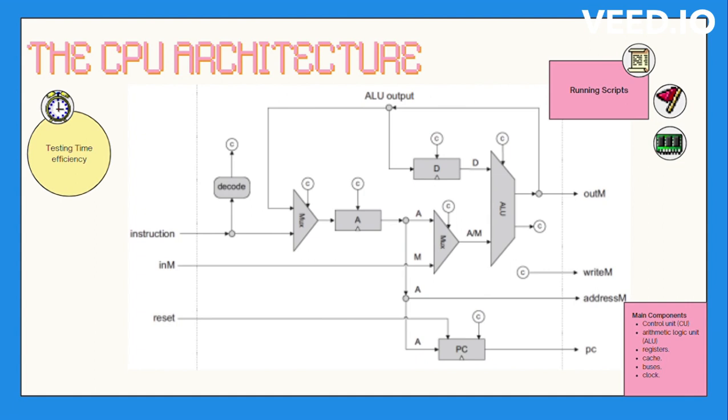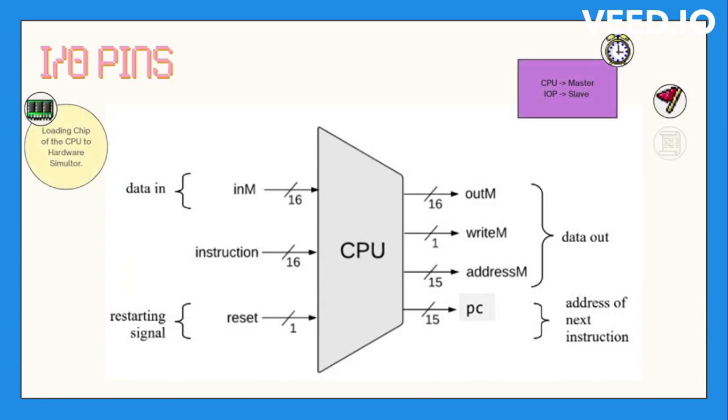So the first step of ours will be deriving the API of the CPU, which just means we have to specify the chip name, input and output pins, and function of the CPU. For now, let's not jump into the logic gates and focus on starting with an abstraction of this chip by having the logic gates in the diagram so we can identify the input and output pins of the CPU. Now, these are the input and output pins of the CPU.